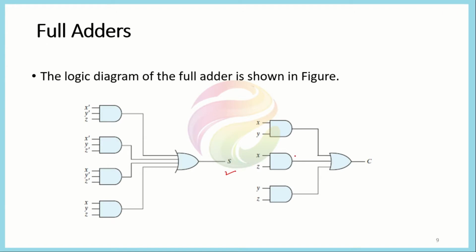For the carry, we again have a sum of product form. These are the three products we calculated, and this is the OR of these expressions, or the sum of these expressions. So this represents the carry. This is the standard diagram for representing a full adder in the form of sum and carry.